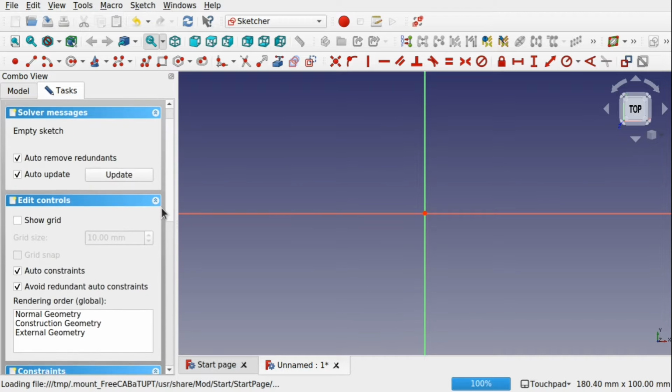It's worth spending some time to actually fully constrain your sketches and deal with problems in there, because you get a model that's fixed and not floating about. So if you have a number of sketches that rely upon each other in a big construction, moving one will jolt the rest, will cause errors, causes sketches to break down and causes problems.